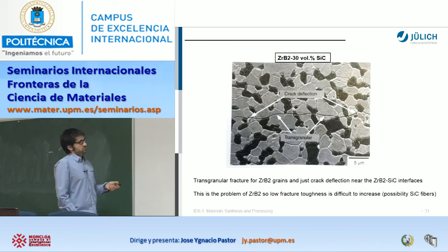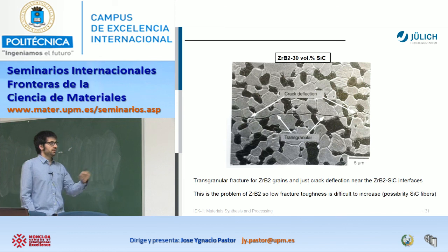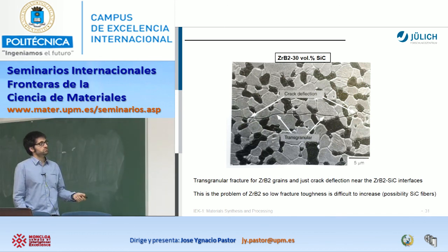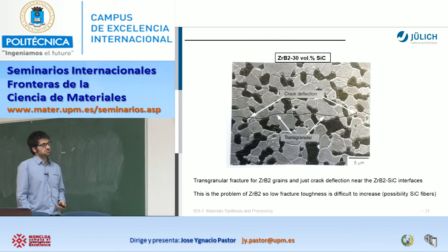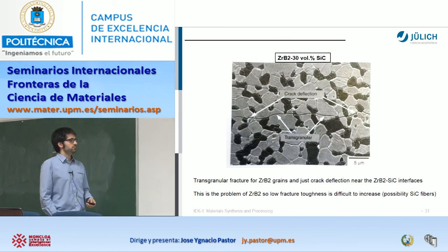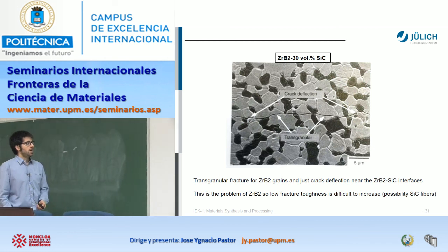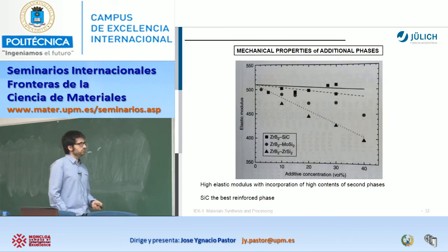The effect is not so much here because the particles are really small and the energy is quite small, but at least you improve your fracture toughness a bit. The idea is obviously to incorporate the silicon carbide fibers in order to get a higher deflection. But even with that, the increase of the fracture toughness is not so high. Well, that is exactly what I put here. Even with that, as you see, the crack continues and continues.